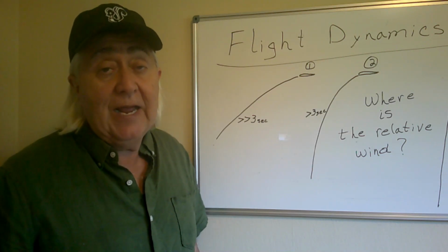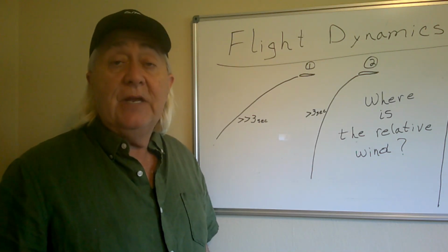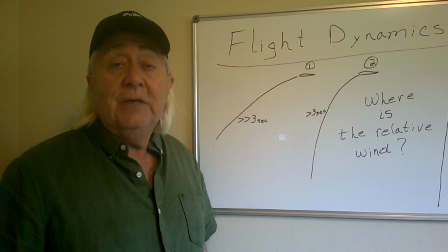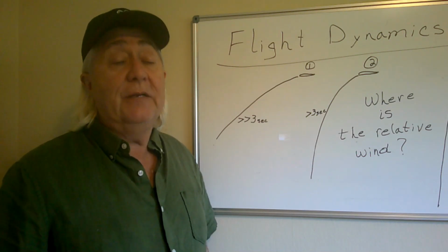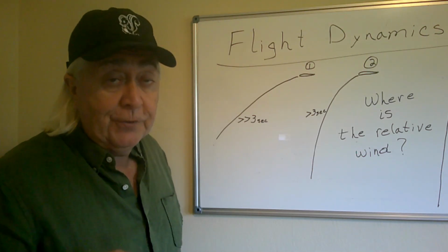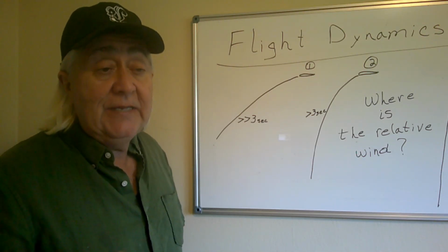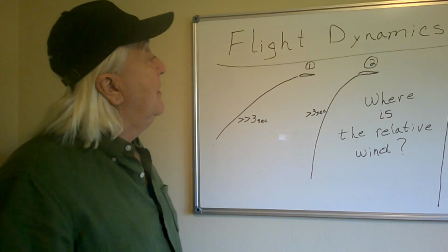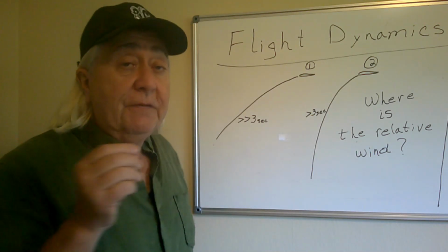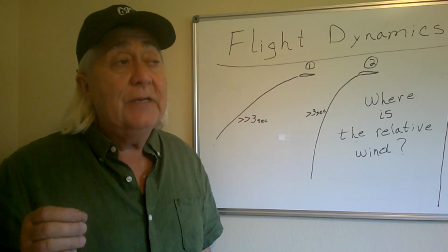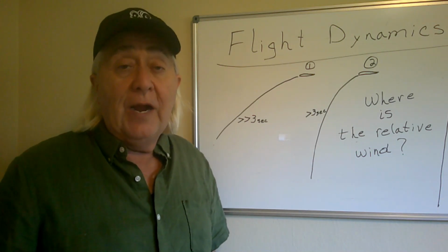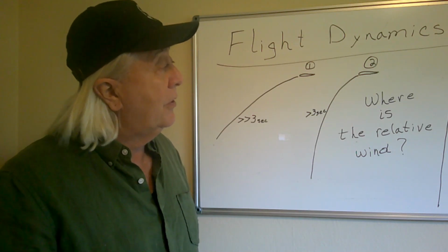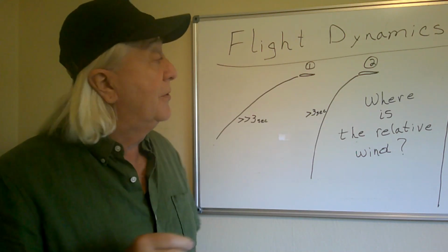The only controls he has are the flaps and the elevons. So he can either put flaps down or up, and he can put elevons up and down. And those forces have to balance out such that he's at a trim speed that he wants to fly at. It's that simple. So if something goes wrong and he can't achieve that trim speed, well, there's a variety of things that could happen. And I wanted to take a quick look at what some people talk about.